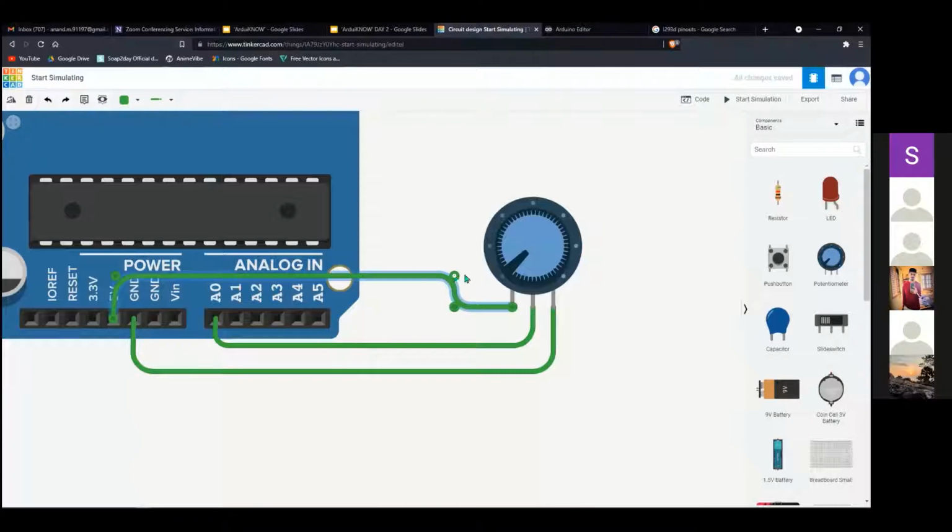If you click on a marker and hover the mouse to left or right, it will move. So I will make it straight. I will wait for the vertical line. If I am getting the vertical line, done. Lock. That gives you a proper connectivity diagram. These points, just click on it and they will go off.